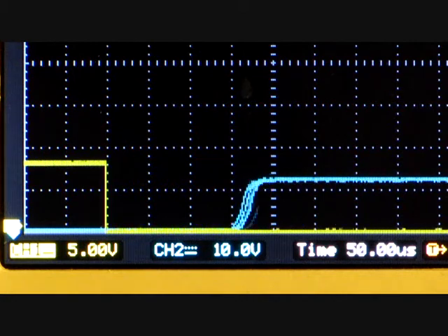So 150 microsecond delay processing, and that includes the opto-isolators in and out of the circuit, and this really doesn't take into account the switching of the power MOSFET, but that's going to be negligible. So there's the biggest delay, is the processing. That's it for this.